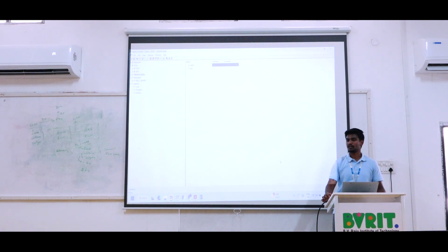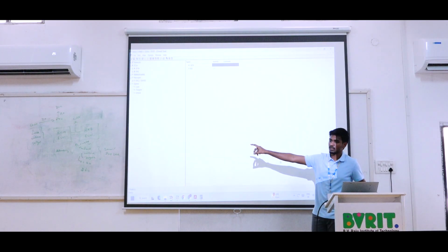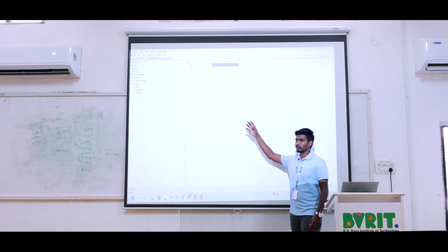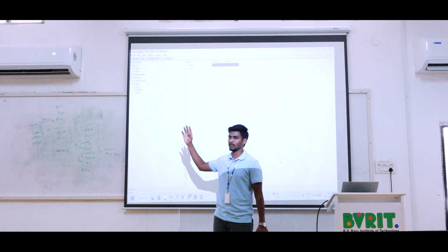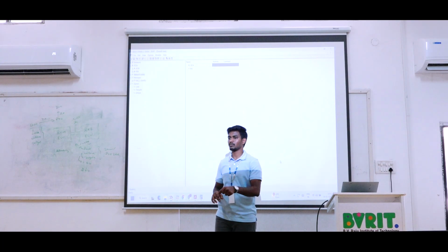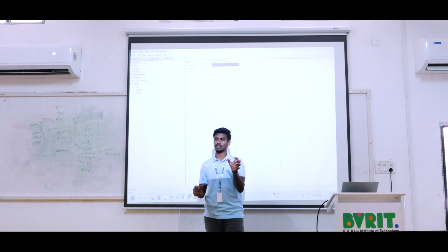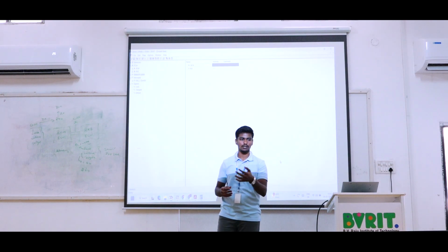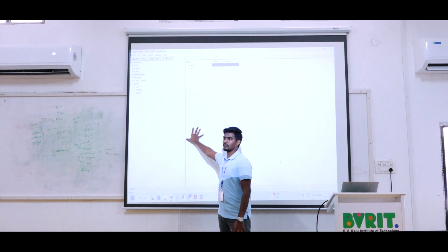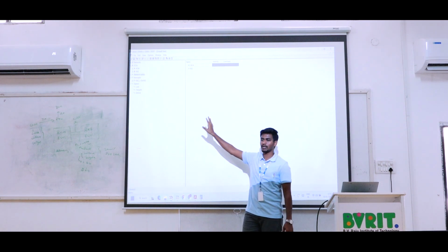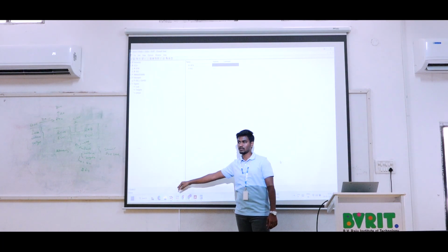Now we have created one database for the transmission of the 2 ECUs, one for RKE, one for PCM. Now we have uploaded this to TSMaster. We are able to transmit ID number 400 and check some performance and statistics, graphical view, numerical view, and we can do some simulation, LED indications, and I am using some logic. Using this database only we are able to do it. But now we have created only the ID number 400. We need to create up to 20 messages, which means 20 IDs.